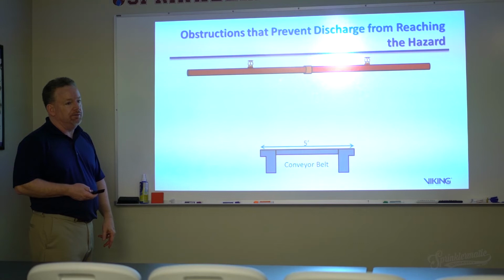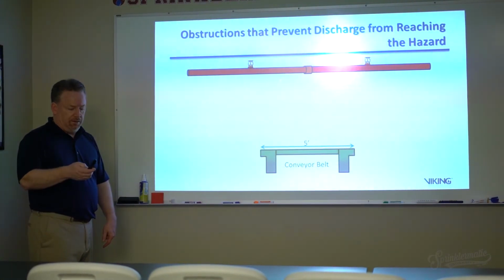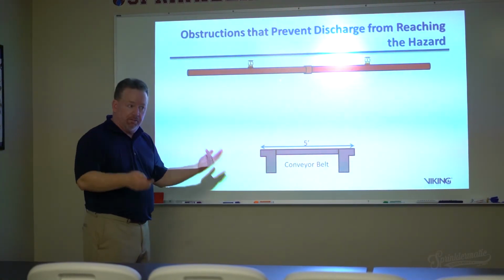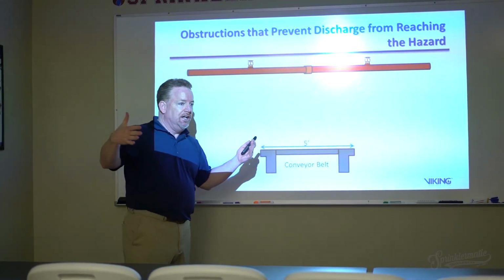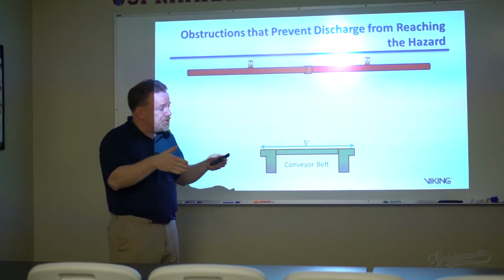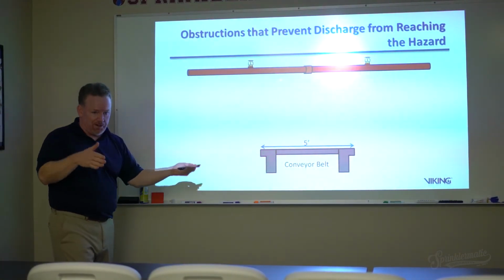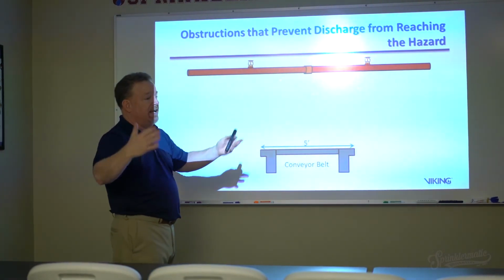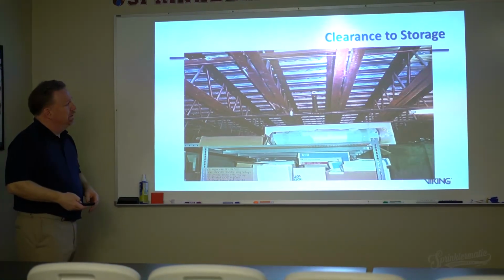Conveyor belts are a big issue. How do you get protection down below? Especially over at the baggage handling facility at Fort Lauderdale Airport. They have conveyors everywhere. Some of them may only be 3 feet wide in some areas, but they all converge in some location. So you may have spots where you don't require sprinklers to be dropped down, but then all of a sudden you've got an intersection or a crossover of these things, and now you've got issues.